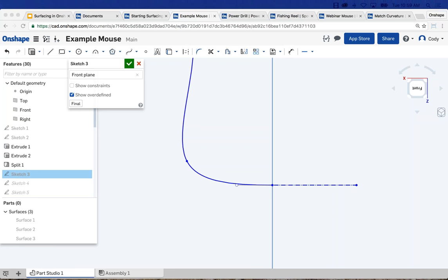If I want to compare a model to a real world 3D object, is there a way to 3D scan an object surface and import it into Onshape? You can scan a model if you have the resources to scan, and then import. We support STL and OBJ, and those are very common formats. So if you're looking for that, make sure it's in OBJ or STL format. We can also import pictures. I don't know if that's helpful for you, but you could import several pictures and use those as references in your sketch.